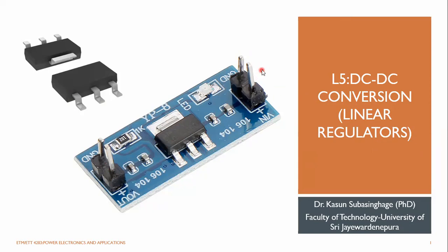So here you can provide the plus and minus of whatever the voltage source. The voltage source can vary. For example, if we take a 12 to 5 regulator, the supply can vary from 15 to 9 volts, but still you will get 5 volts clean output DC voltage. So that's the purpose of having a DC to DC converter.